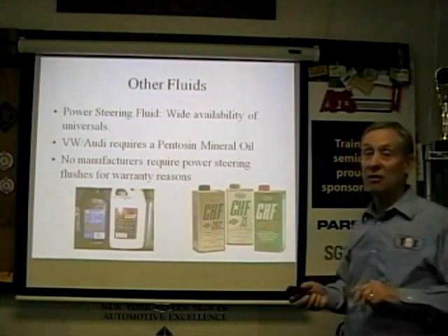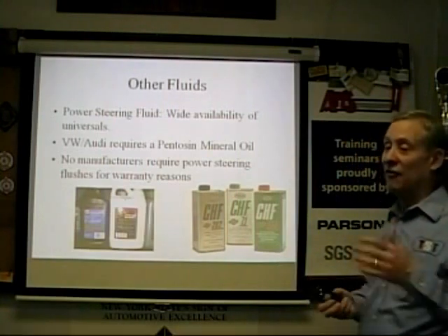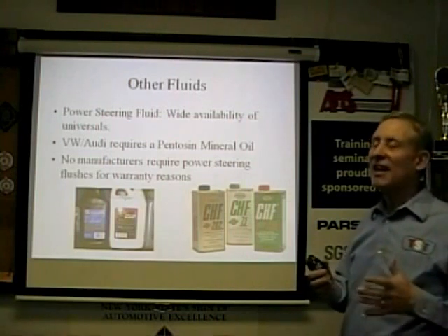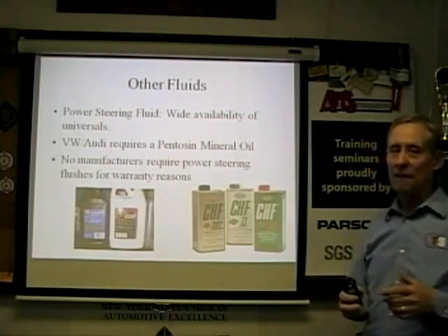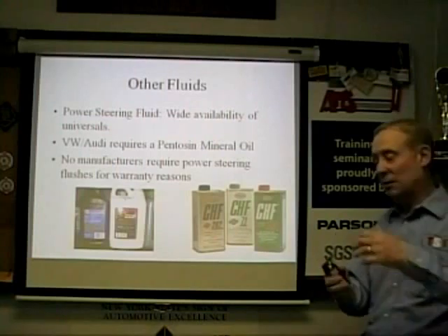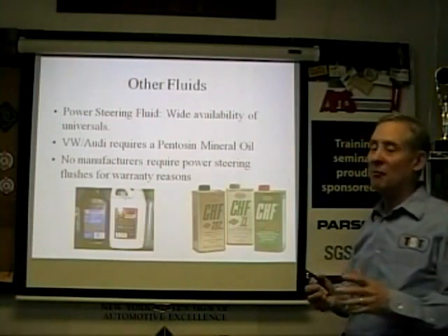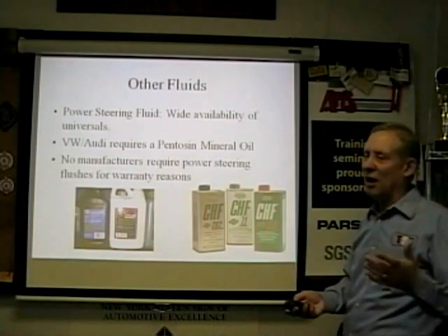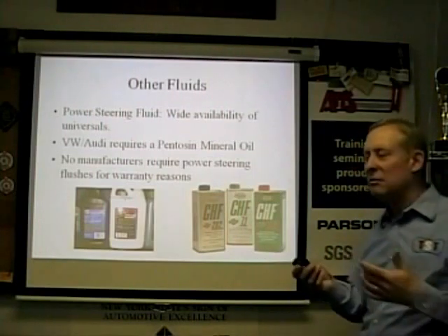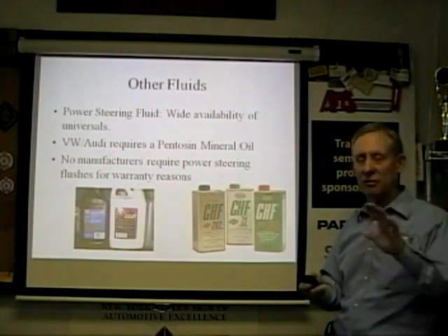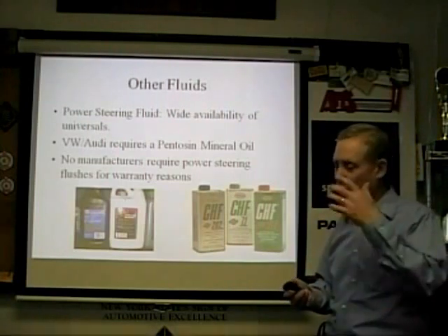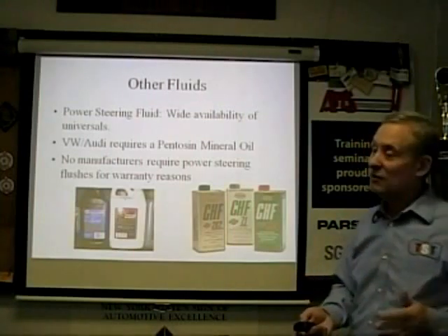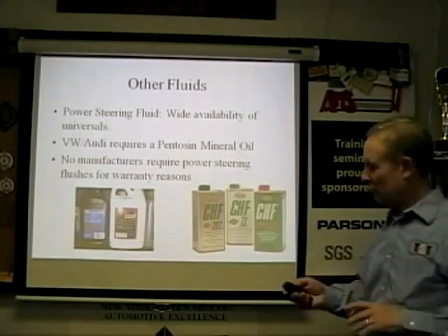However, just be aware, most manufacturers today have a filter that's replaceable in some form in their power steering, and there's no real stated interval for most of them. Sometimes it's the whole canister, sometimes it's a replaceable filter. Bottom line is, you have to use your own discretion and experience. I usually say 75, 100,000, some high mileage. At some point, you recommend changing the filter, however it's done, and flushing the system and putting maybe a couple of hoses. Certainly, if the thing develops a leak, recommend replacing.